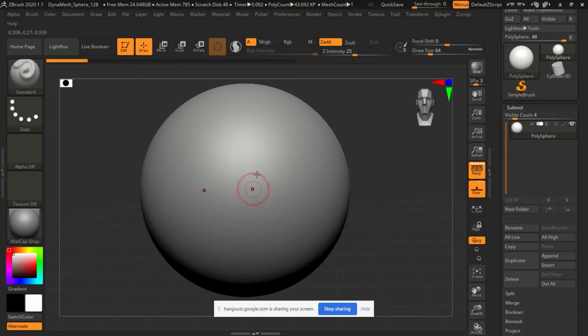Also by default, you'll notice that when I hover over my model, I have two different red cursors following, sort of mirrored. This is the mirror tool, and we want to turn it off, because it causes issues later when we're trying to optimize. Photogrammetry models aren't perfectly symmetrical, so we try to preserve that detail.